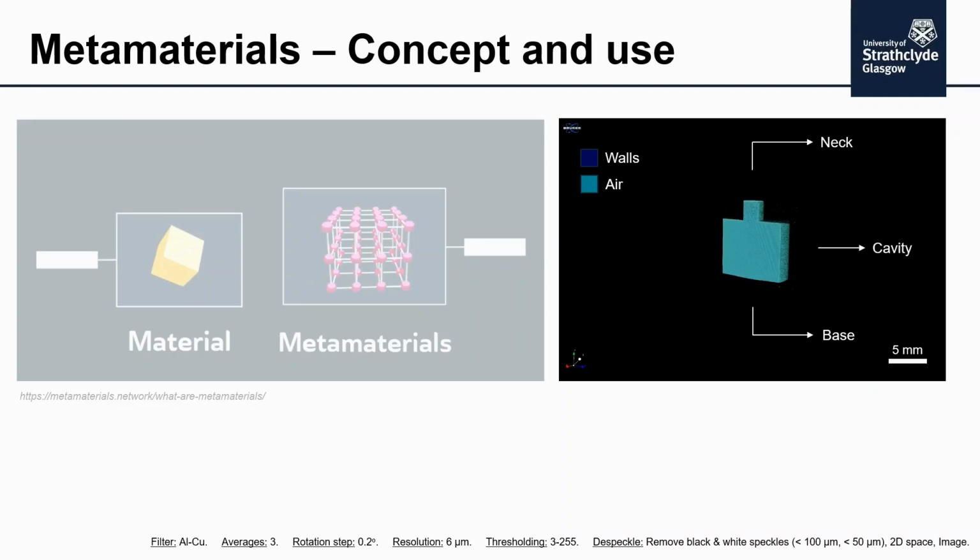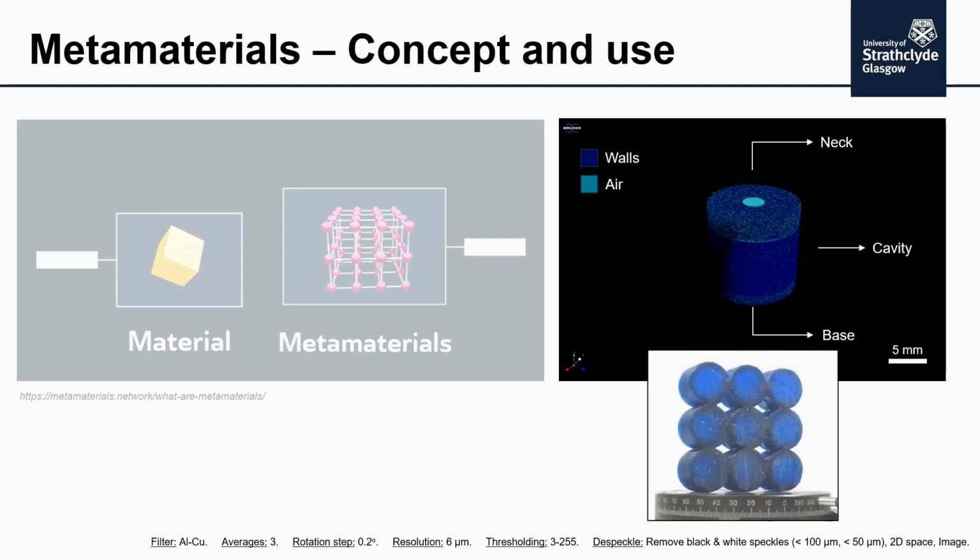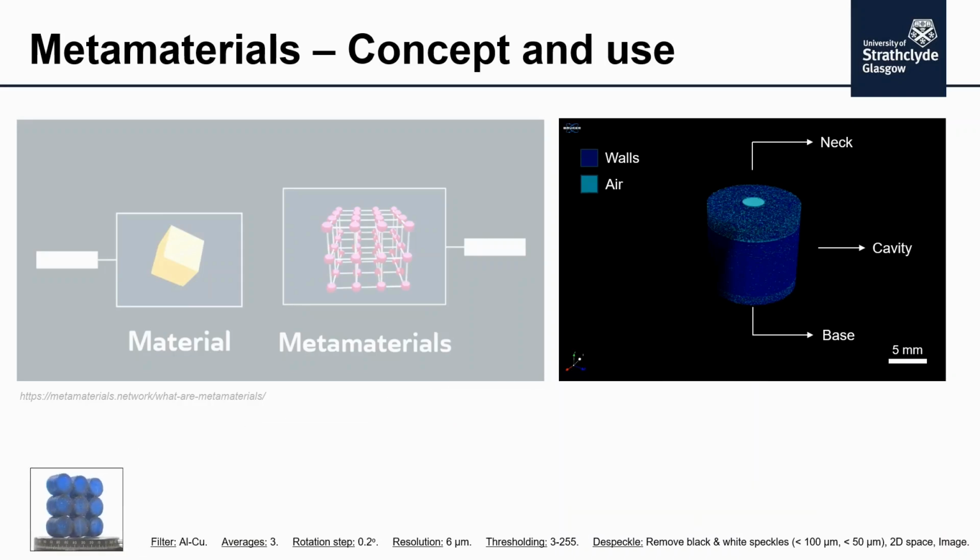They've been known and very well studied for like 2 centuries. And it's well known that their acoustic properties only rely on their geometry and their morphology and their dimensions. So what we can do is to develop or just calculate the dimensions of these resonators to attenuate sound at a certain frequency, and then we can arrange them in this n-by-n structure in order to enhance sound attenuation.